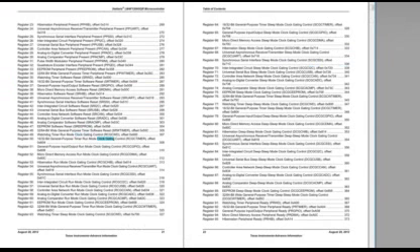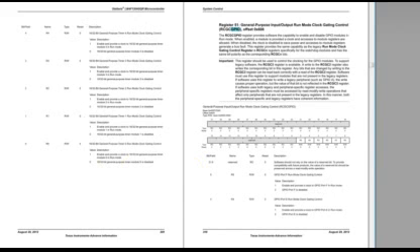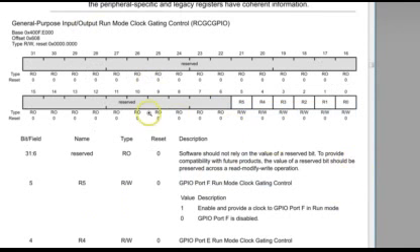Oh, here is something interesting. Let's go to that page. Let's search for the string GPIO in this section. Oh, here it is, the GPIO clock gating control register. Let's take a closer look at the register description because this is a very typical format commonly used in datasheets.